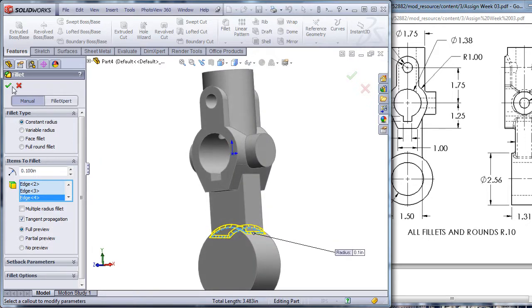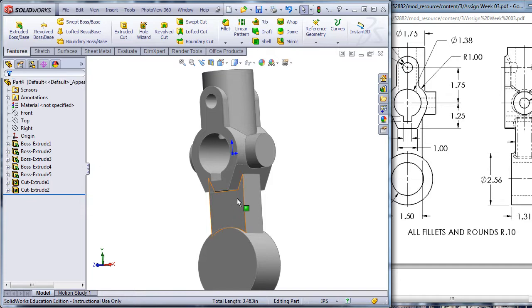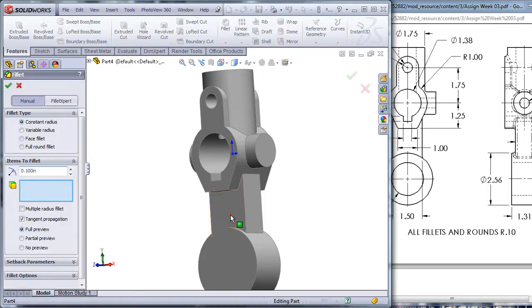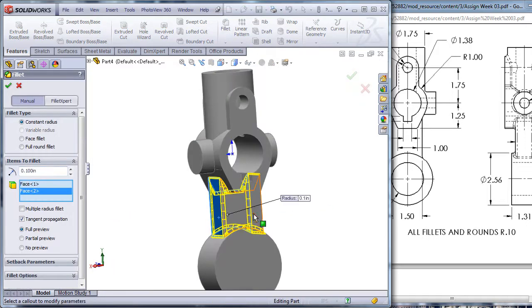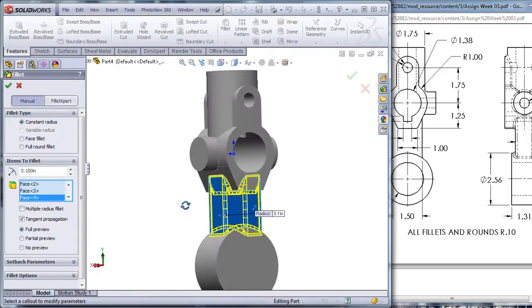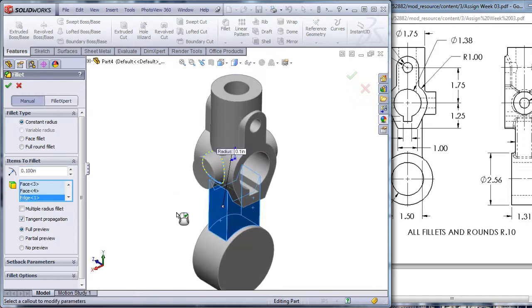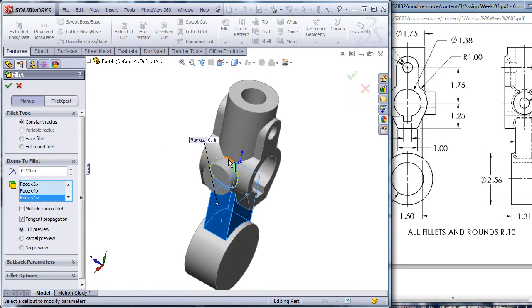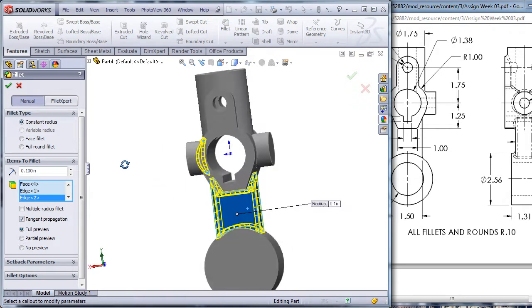However, on a part like this, where certainly all the corners are filleted for the rectangular flats, let's try doing a fillet. And we'll just pick the faces. I'm going to still pick all four, but it's a lot less clicking. Then this is filleted. And notice it can't complete the tangency here at the top corner, so you've got to pick that to get that fillet to show.